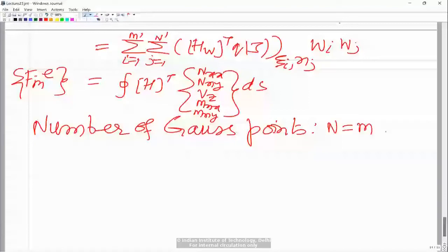Now, if you look at the same rectangular element in the physical coordinate space, although actually the element can be any arbitrary quadrilateral, the n and m are coming out as 1.5 and we are using 2, so it can even handle slightly non-rectangular elements.